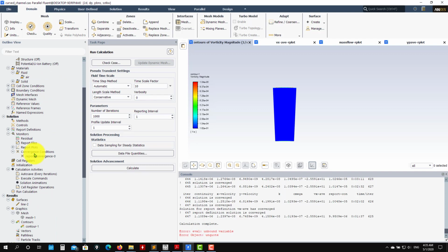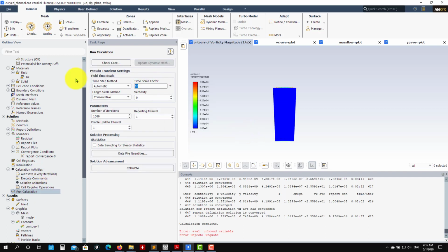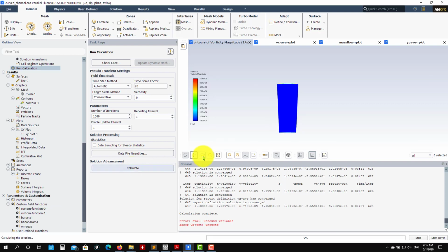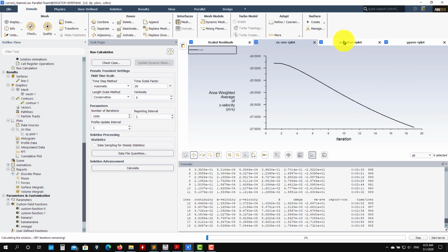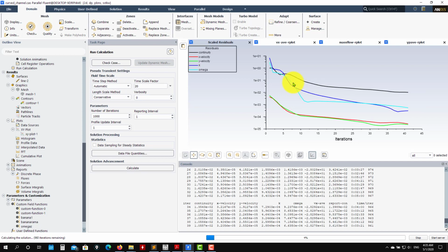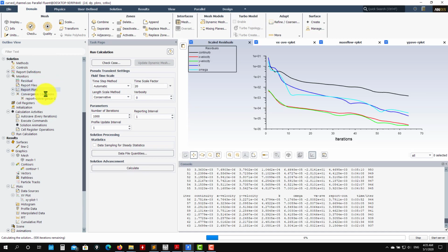You run in the usual way. So let's run from scratch. Let's start from scratch. And I will put here 20, because I think it will work as well with 20 to reach a faster convergence. And let's see what we have. All these definitions are also still valid. Launch. Okay, see that all your monitors, you have them there. And let's see when we have a condition where we meet all these criteria.